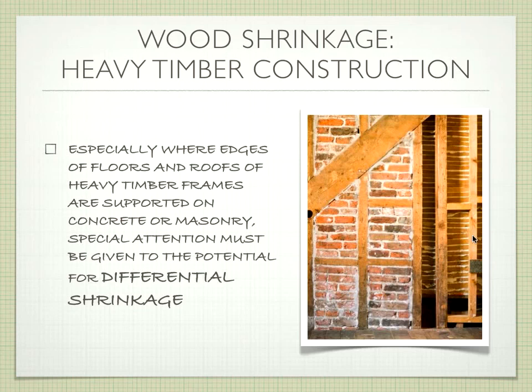Okay? So the problem is, as soon as you do something like this, we talked about the fact that wood inherently shrinks. You guys remember? Which direction does it shrink more? Tangentially. It's an impossible word to say, okay? Where does it shrink the least? Yes, the length. So that presents a little bit of a problem because does brick shrink? No. So brick doesn't absorb water and expand or lose water and shrink.